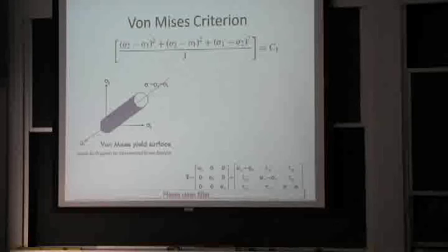And what I'm going to talk about on Monday is how everything you've learned before has been uniaxial tension. You learned about tensile tests? Well, what in deformation is uniaxial tension? Nothing that I know of. Everything is biaxial or triaxial, okay? And so, for my part of the course, you're going to have to learn about biaxial and triaxial, and they'll put up the von Mises ellipse.